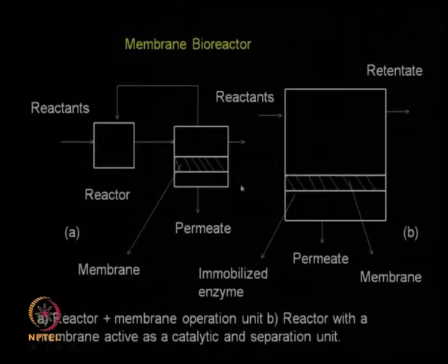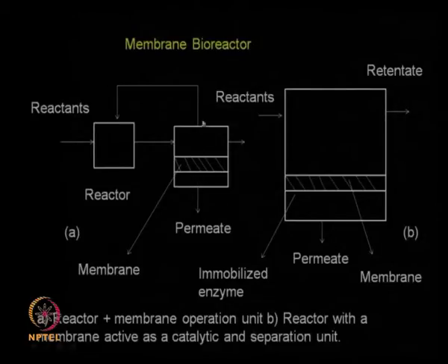So in a normal conventional fermentation we just stop the reaction, but if I have a membrane I can continuously remove part of the alcohol that is produced and the remaining active biomass can be sent back. So the advantage is the concentration of the alcohol will be much lower all the time in your reactor. Okay. So that is the main advantage of this type of setup actually.